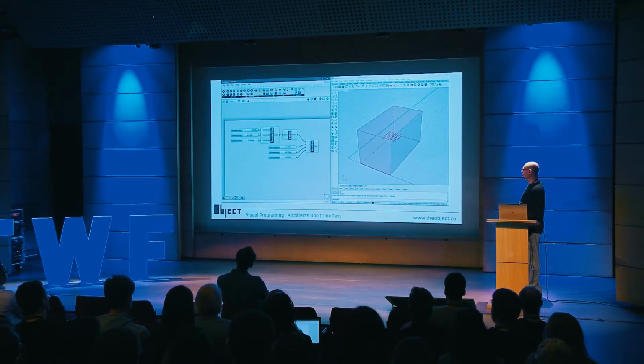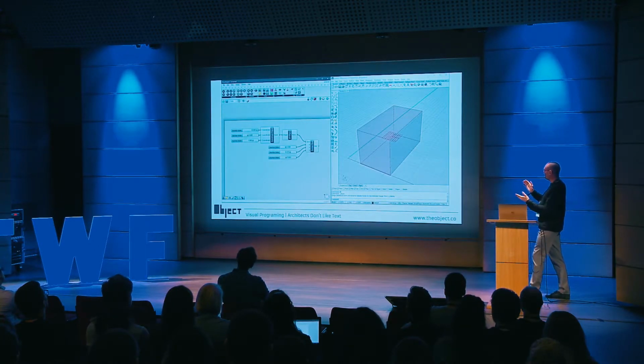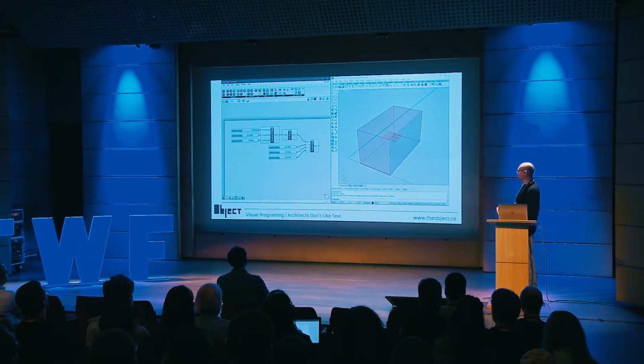And each component recreates one of those lines of code. You have the construct point, which gets the 3 coordinates and creates a point, which then creates the plane, and then finally we have a box. You can see the box on the right, it's Rhinoceros. And for me as an architect, this is way better, way easier, right?